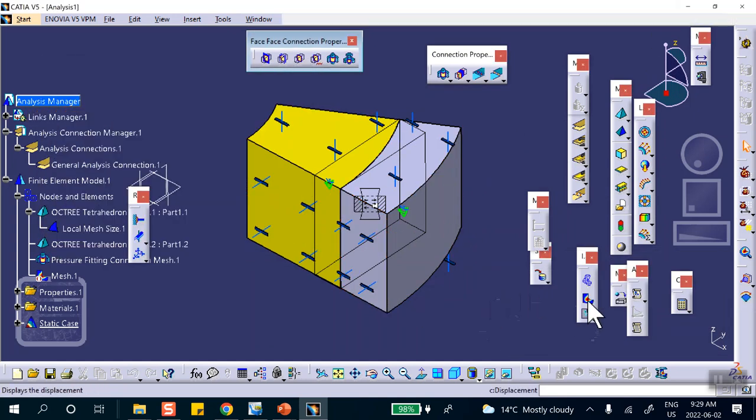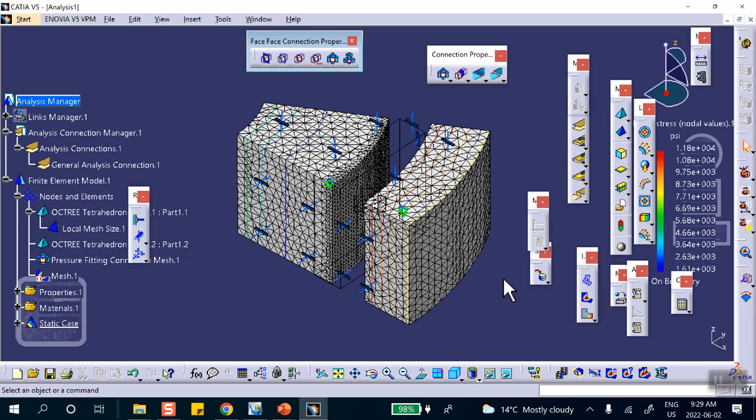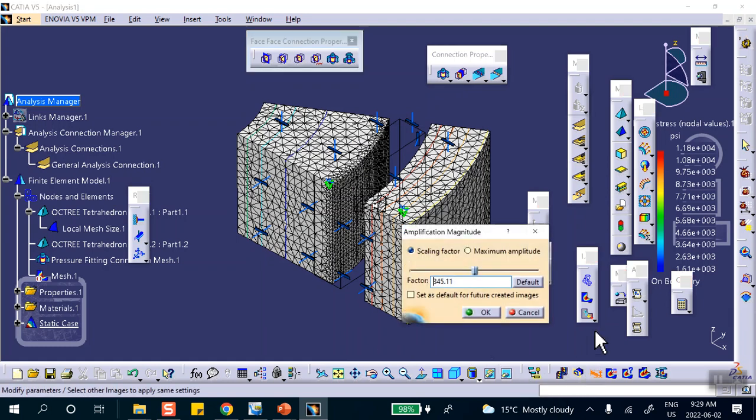All right. First of all, von Mises stress. The reason this is happening is that the scale is magnified, because otherwise you can't see. If you want to see the real thing, set the scale to 1. There is a reason: it made everything 345 times bigger.